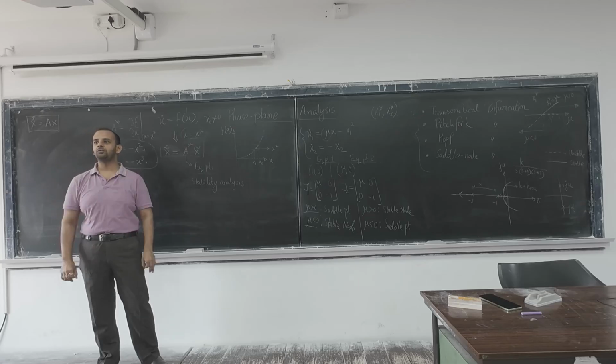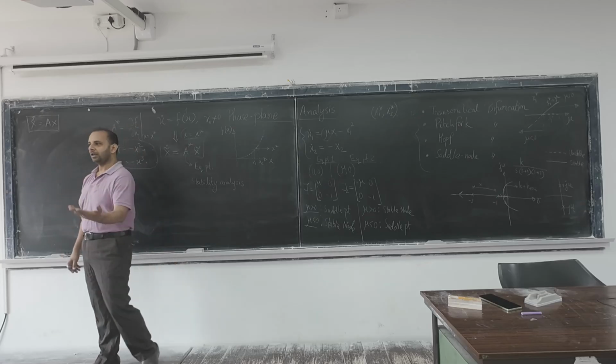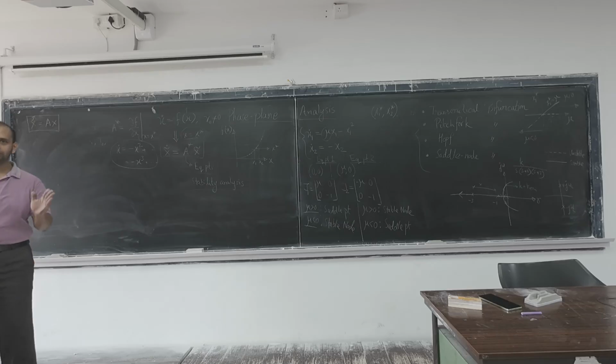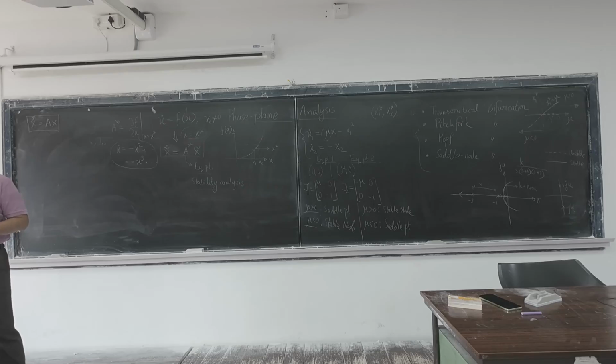You cannot expect that whatever the variation, 5%, 8%, 10%, 15%, the robust controller will be a superpower controller that can handle anything. It is not at all. There will be a certain parameterization, and with respect to a certain bound, if we design the controller properly, it will handle it. But if the variation is beyond that considered range, the controller will again lose its accuracy.